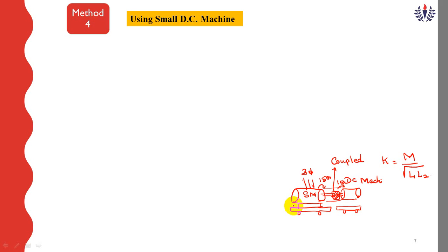Sometimes, even though the windings are perfect, the machine runs at only 495 rpm. It won't run at 1500. To make that machine run at 1500, they need a device to connect. For that, a cheaper device, they will take a DC machine. This is one of the testing arrangements.